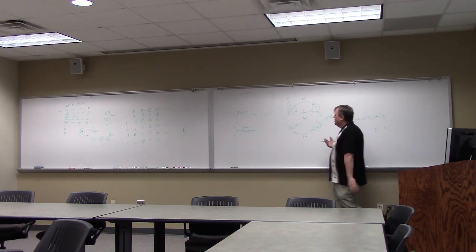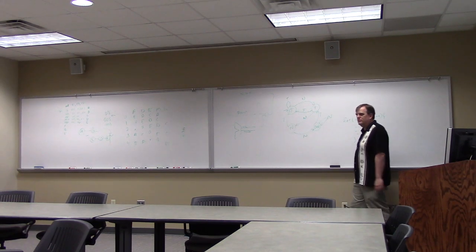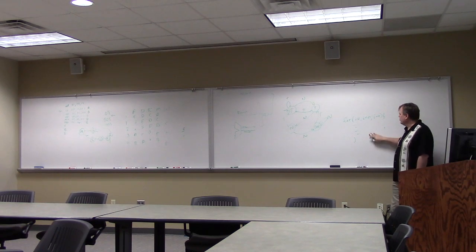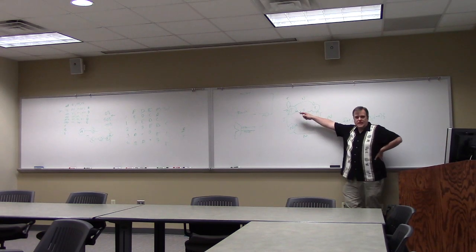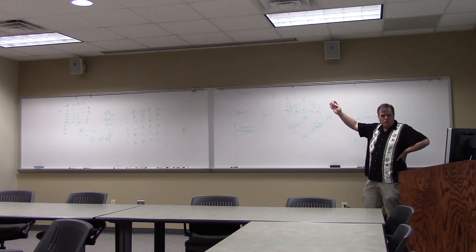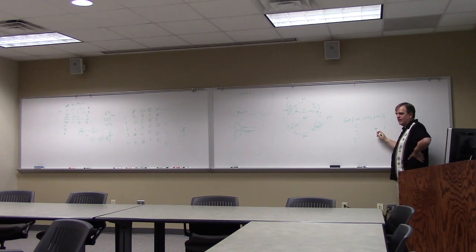So I submit to you that if you looked at something like this, typically you start here, that's your start state. How correct would it be if I went even to my simple case with 10 things in there? It would be right 9 times, right? Because it keeps saying taken, taken, taken, taken. It would be right every single time, no bubbles, always guessing correctly. One time it says taken and it wasn't. It was wrong one time. So what's my correctness percent? 90.